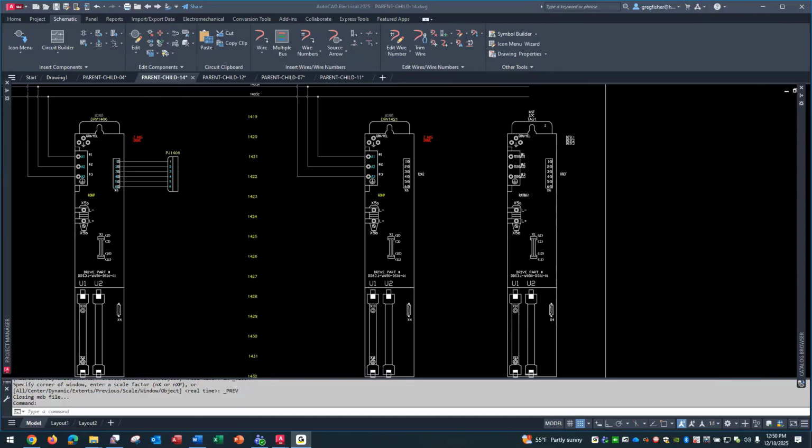It says if you have a 4 NO contact relay with coil and pin list defined and add a contact block adder 3/1 and set the pin list up for the adder block, will all available pin lists be available as you add the additional contacts? Yeah, I mean you can build that into the catalog number. If you use them, you use them. If you don't, you don't. So you can absolutely set it up like that.